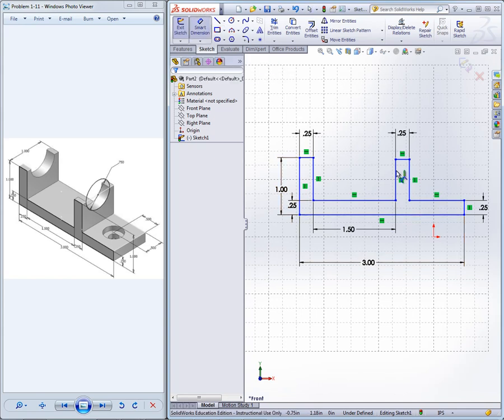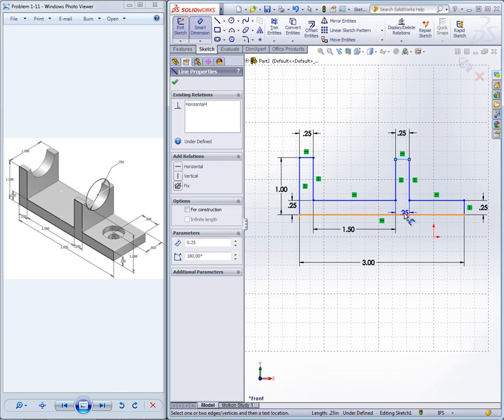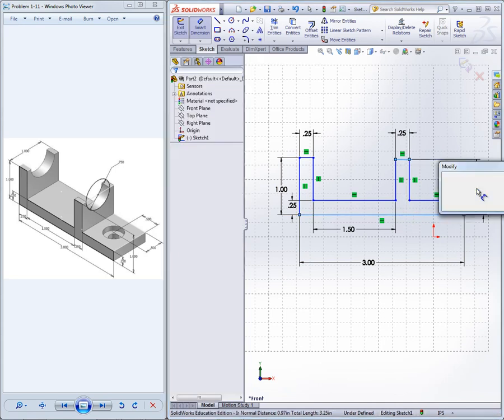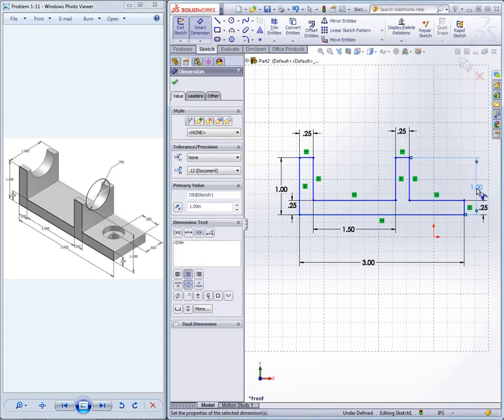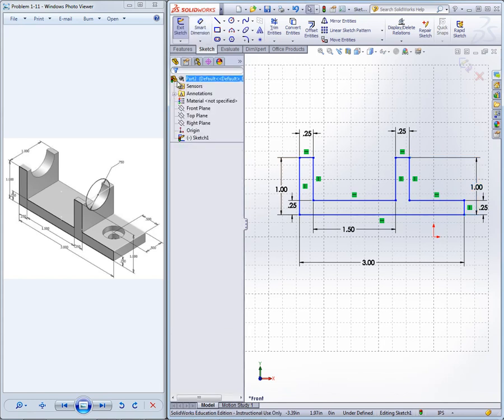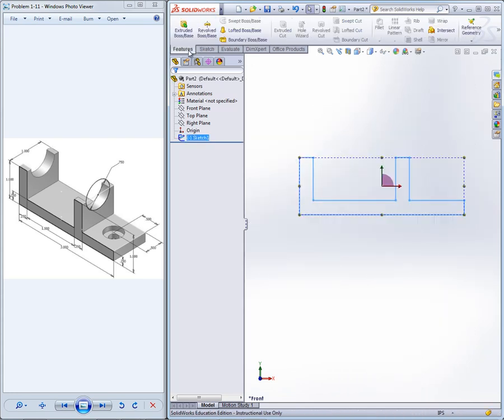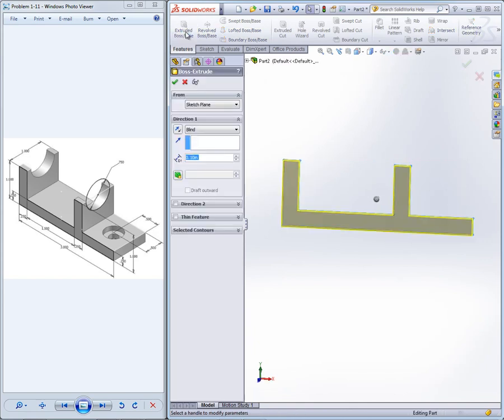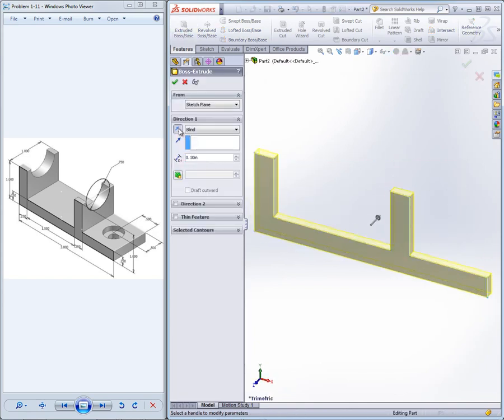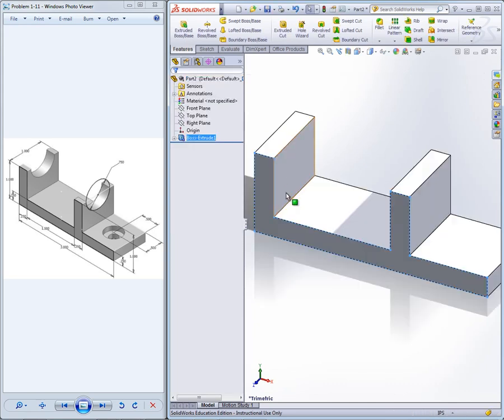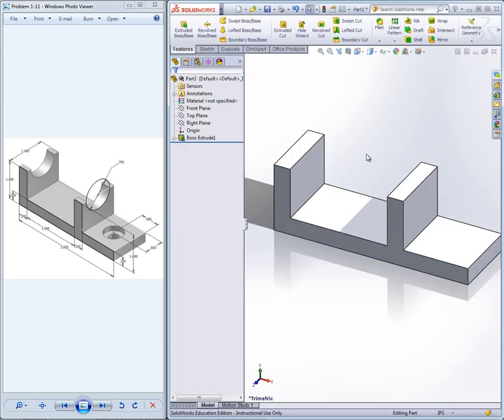I need to make sure we've got... that's what I suspected. Enter a 1. Then we'll left click on the green check mark. Then we'll right click, left click on Exit Sketch. We'll left click on the Features tab. We'll left click on Extrude. And we'll flip it to the other way just for something different. We'll enter a 1. Left click on Enter. Left click out in the workspace. We'll scroll it back a little bit.